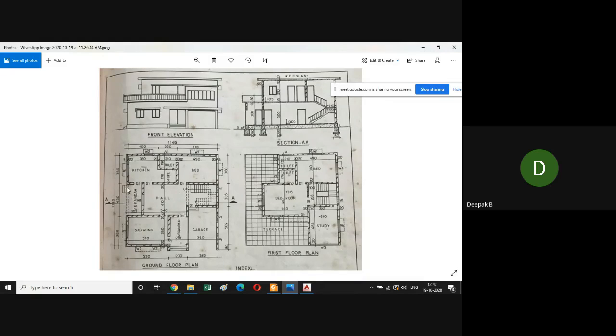all the lines that are not visible at that particular level, we show with dotted lines. This is above the cutting plane, these dotted lines that we see here. And in the case of stairs also, from here it is going to the first floor. Up to that height only will the edges of the stairs be directly visible to us. So for the upper stairs we are drawing it with dotted lines. So this you can draw with the dimension that is already available with you.